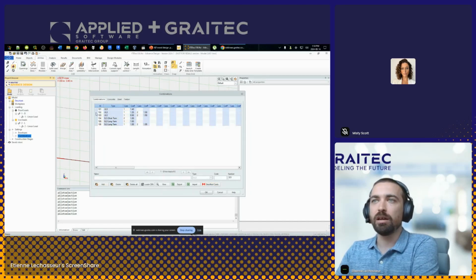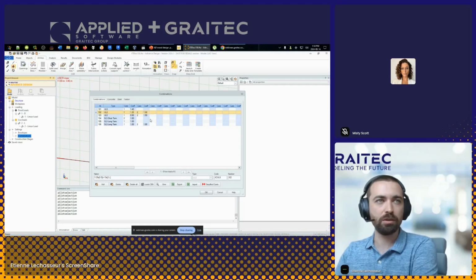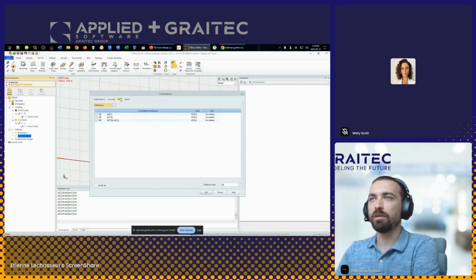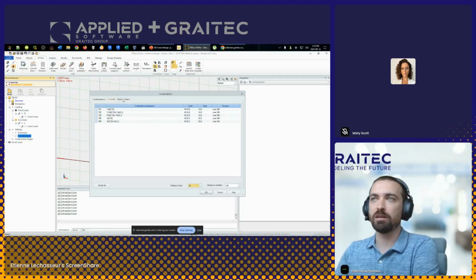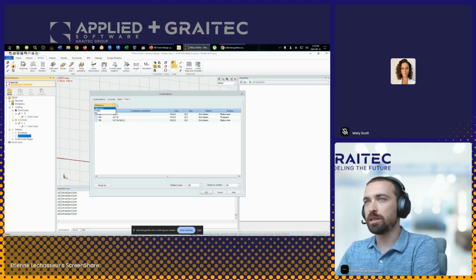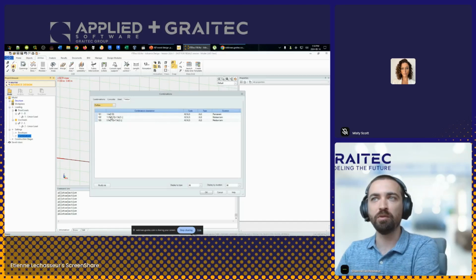that I need. The critical one will most likely be this one here, the 102 with 1.5 times the live load. What's important with the load combinations is that if you create your own load combinations, you have to include them for each material that you want to design. So if I go to timber, as you can see, there is a list for which ones are going to be used to verify the deflection and which ones will be used to verify the resistance of the profiles.